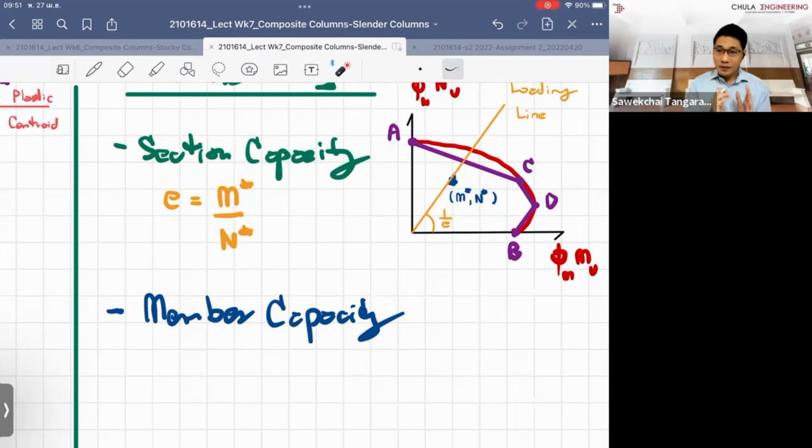It depends whether the problem you're looking at is restrained from sway or unrestrained from sway, right? If it's restrained from the sway, the discussion that we had now works. If it doesn't, of course, you can go back and look in the concrete. They have another way of taking into account the unbraced, or sway, column, right? So we go back and talk about this again.